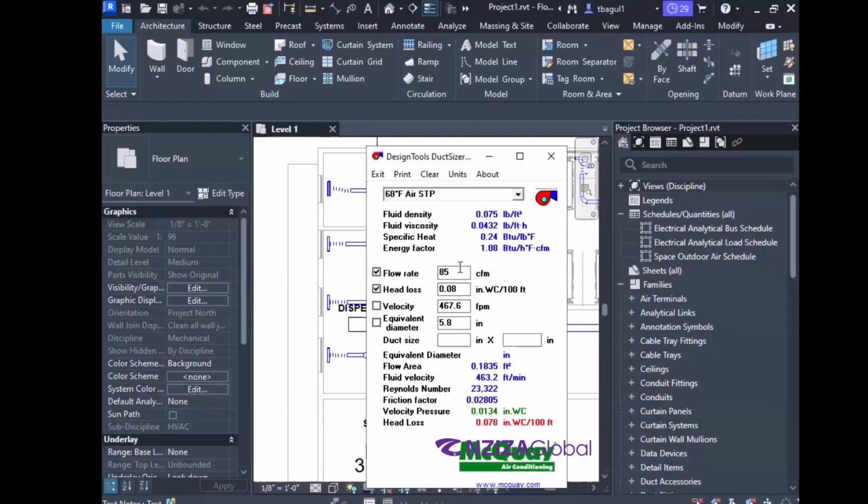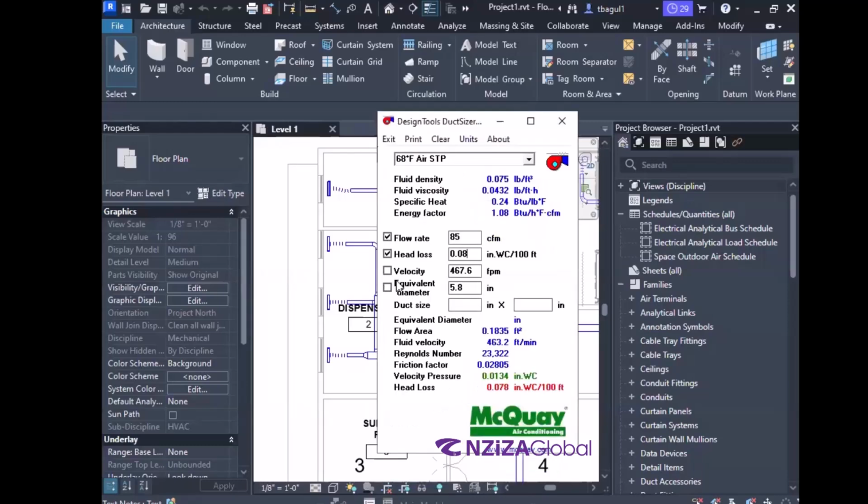All right. Now, over here, you see there are still more check boxes. Okay. To get the adequate size of the duct, you need to have at least two parameters that you are feeding into the duct sizer tool. It can be either CFM or head loss. If you are restricted with air velocity, you can even have the air velocity entered over here, right? But you need at least two parameters to get the rest of the parameters. Is that making sense till now?